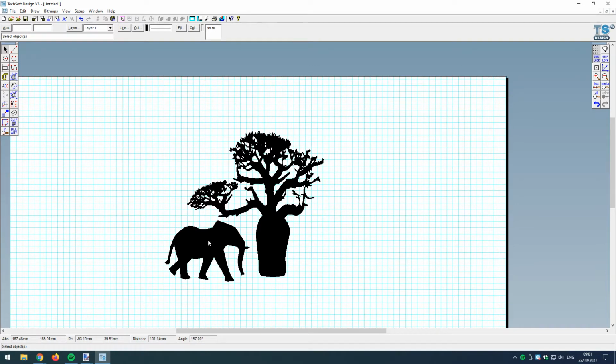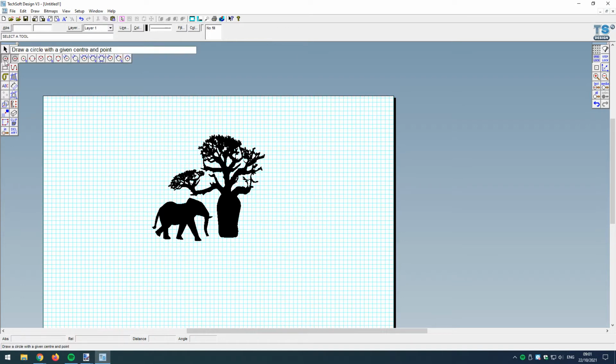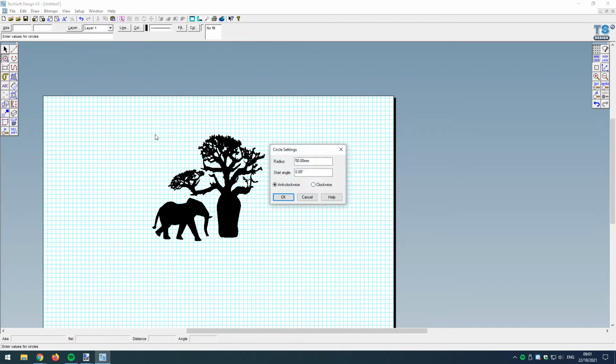Now I'm wanting this to turn into a clock. So let's just imagine how this might look. I'm going to perhaps get a polyline tool here. In fact, no, actually, let's just get a circle tool first. I'm going to get a circle with a fixed radius. Let's go here with, let's see, the size I'm looking at is 145 millimeters across. So I'm going to make this 70 millimeters radius.